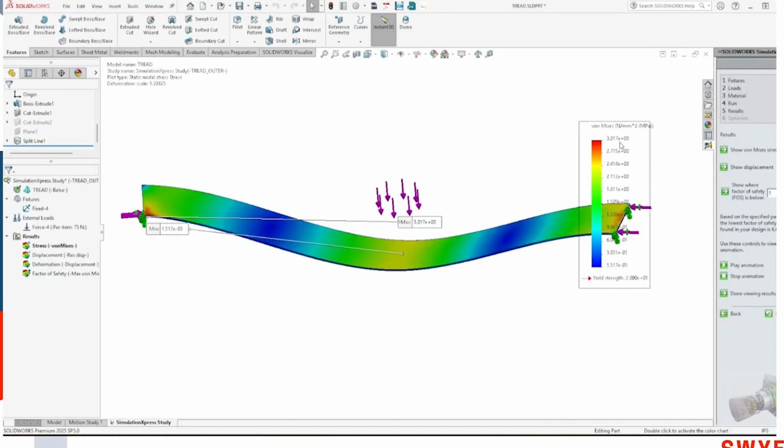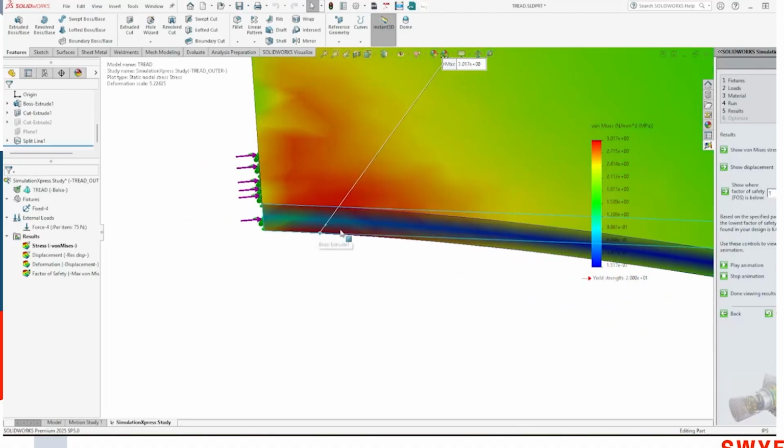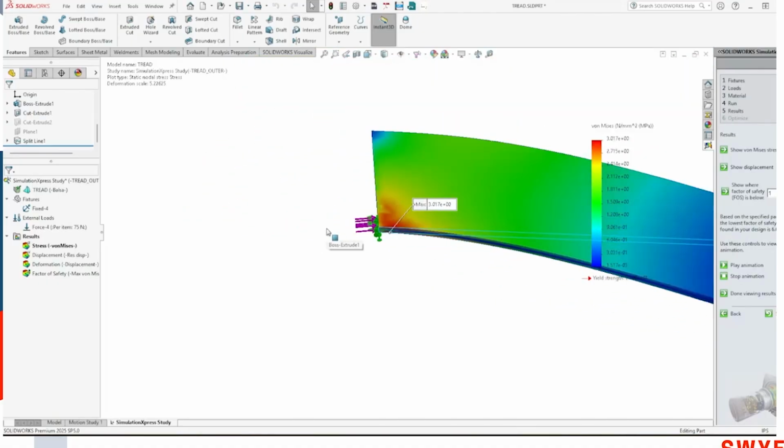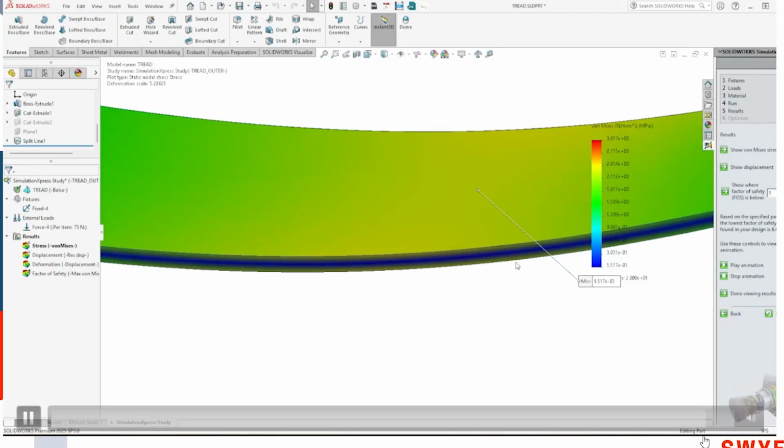Okay, now looking back at this, our stresses are slightly different. And we see our deformation scale is completely different. The scale is smaller, but the image has moved the same. That means that the wood is actually seeing higher levels of stress because it doesn't have to scale it up as much in order to make it move that far.